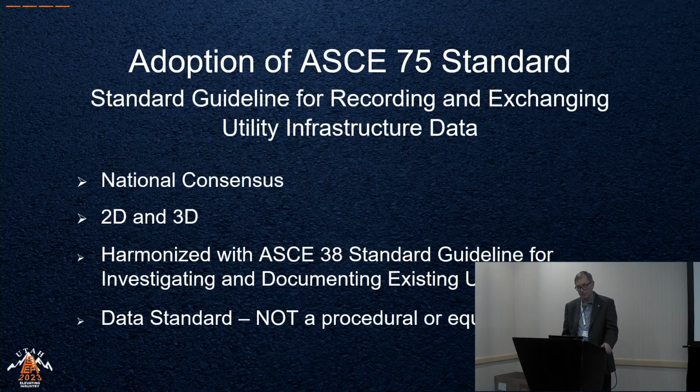It's harmonized with the ASCE 38 standard, which has been around since 2002. This means that the definitions are the same between the standards, and they've eliminated any overlap between the two standards. Lastly, it's not a procedural or an equipment standard. This does not tell you how or what equipment to use when you do surveying. It's strictly a data standard.